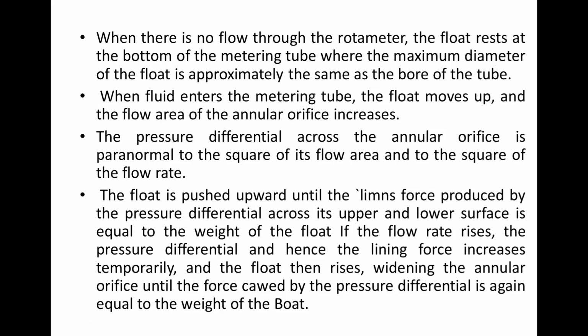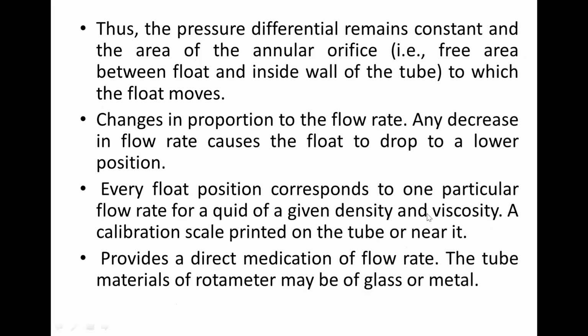So the weight of the fluid, if the flow rate rises, then the pressure differential and hence the lifting force or the drag force increases temporarily, and the float then rises, widening the annular orifice until the force caused by the pressure differential is again equal to the weight of the float. The float is also called the boat. Thus, the pressure differential remains constant, and the area of the annular orifice, that is the free area between the float and the inside wall of the tube, through which the float moves,